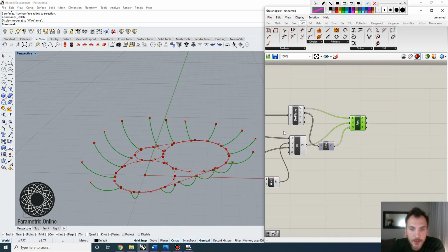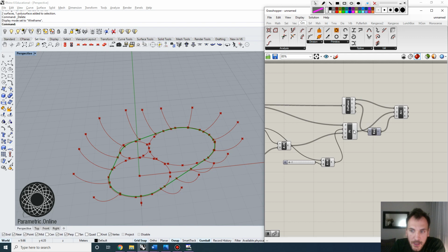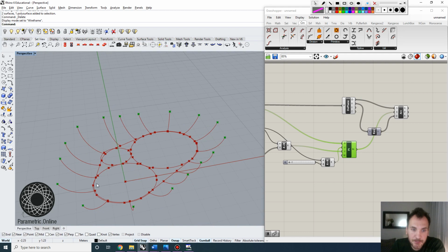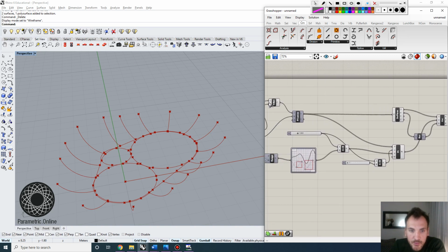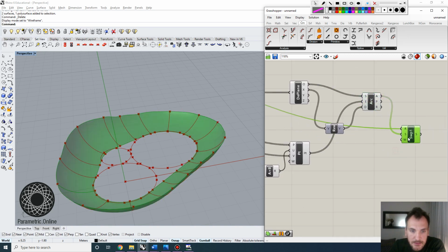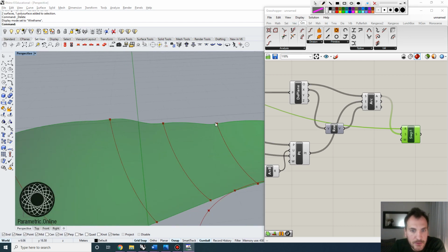So in the next step, once you have these arches, let's see what we have. We have this filleted curve, and we also have these points. There are two ways of combining these profiles. You can use sweep one. Sweep one will take in, just like the Rhino function, a rail curve, which is this fillet curve, and it will take in the segments or the sections as the arches. But if you zoom in here, you will see that the geometry is actually not doing a good job of creating these connections, right? So that's kind of messy connections.